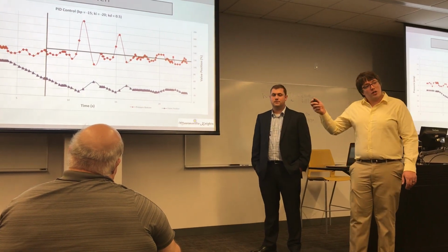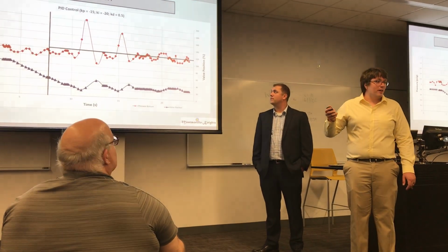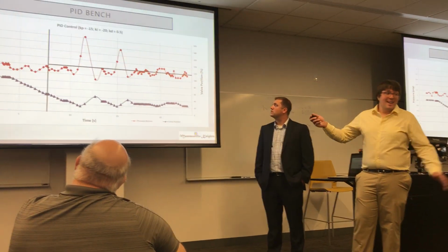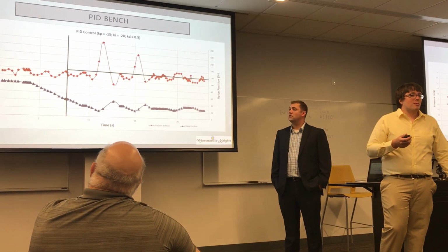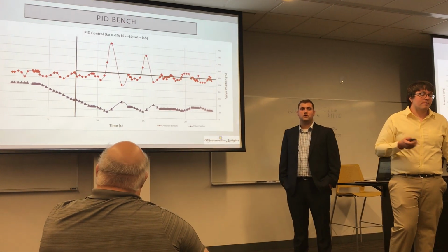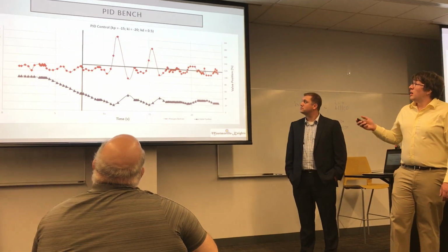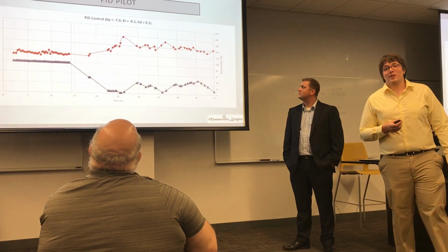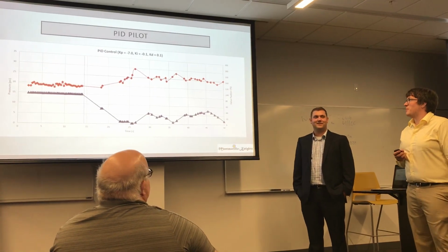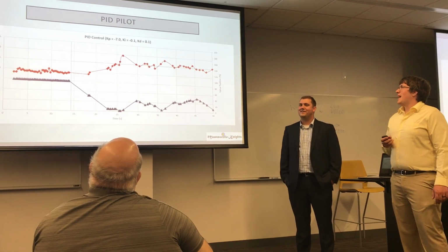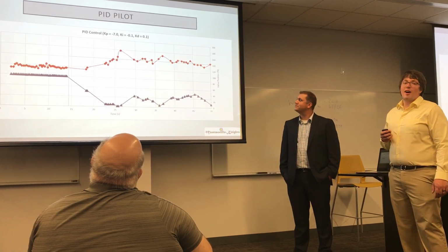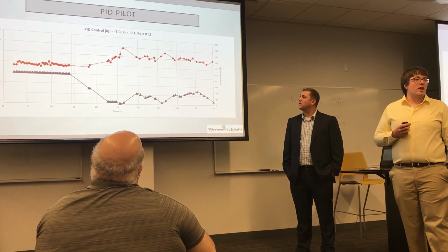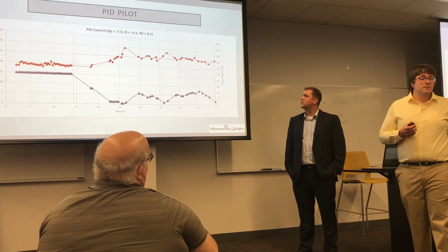Those two large humps that you see are actually overshooting. And if you look at the top of the graph, we even used a bit of a derivative gain, and still, because of that closed region I talked about, that little bit of overshooting still occurred. To no surprise, the PID of the pilot model looks pretty similar, so there's no suspense going to be built up there. We actually had the set point about 25 psi on this one, and again, it doesn't look like it exaggerated as badly as, say, a static control.